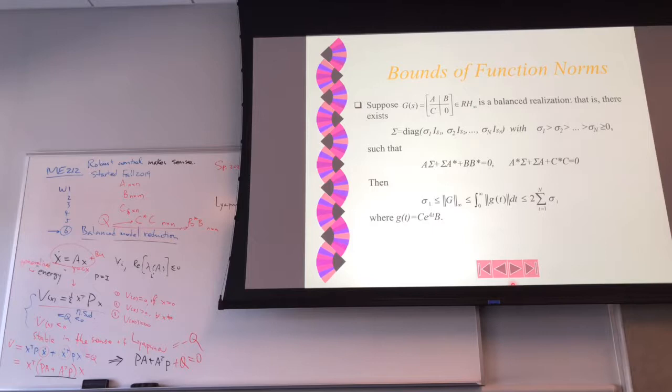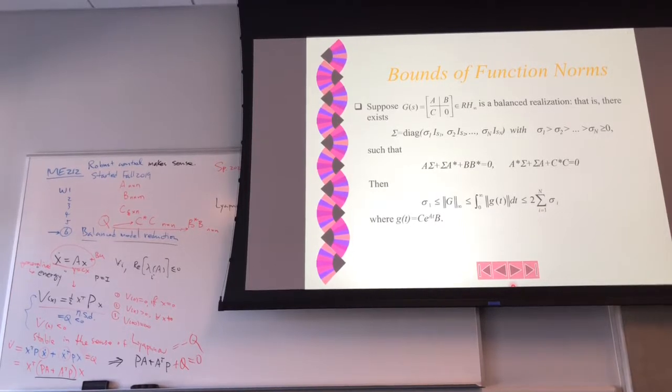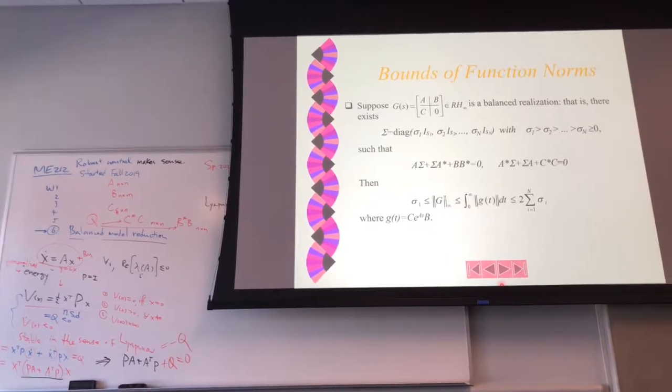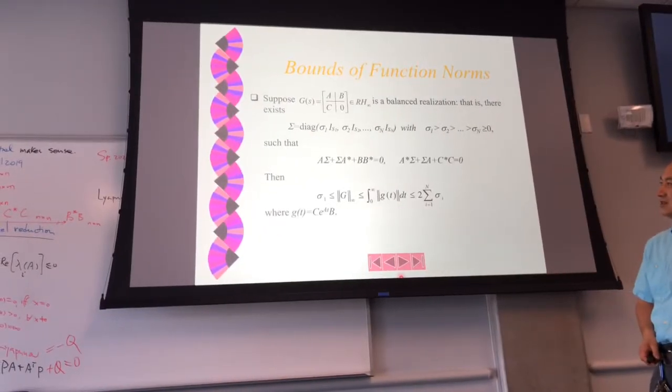So basically, you give an impulse, the system will respond and decay to zero. Now, what's the area of that? The system will react to the impulse and then get to rest again. So that kind of area in that impulse response is finite, but the area is greater than the G infinity norm.